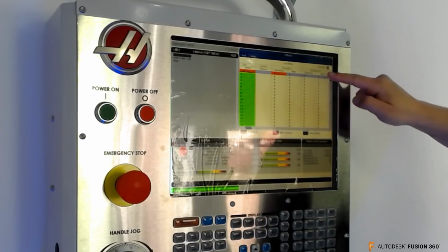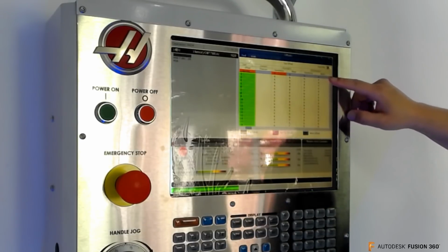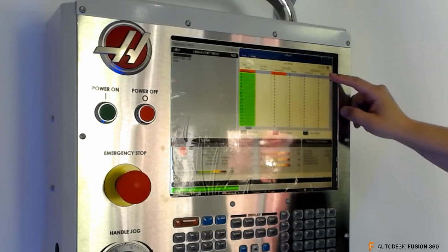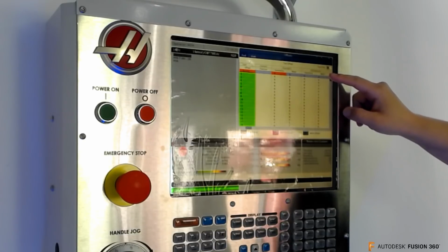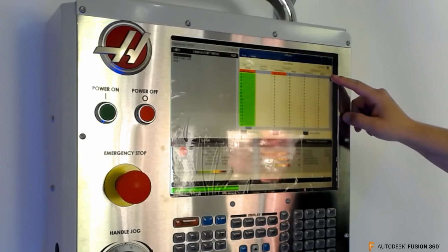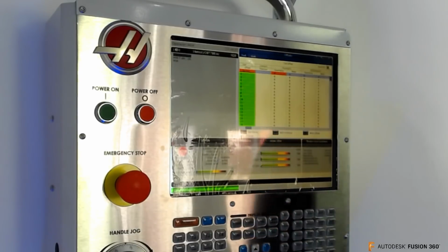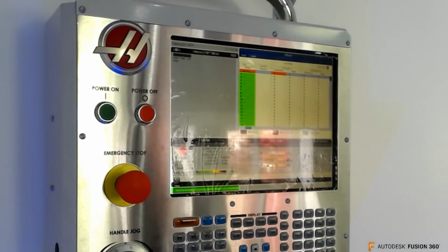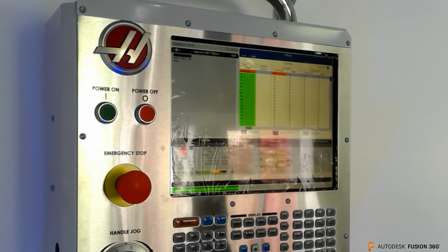The next line is wear, and this is where you can insert the diameter of the cutter if it wears down. And normally a standard end mill in the United States, at least, I should only talk for the United States, is plus nothing minus 3.